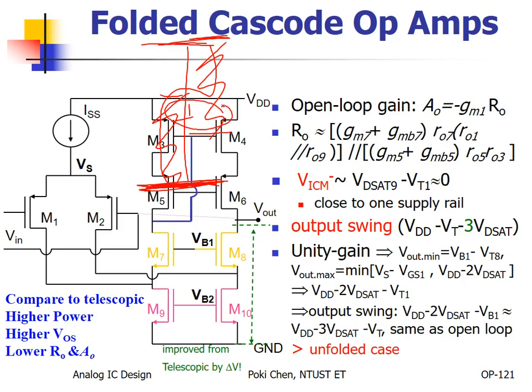Those differential inputs are active, are functional. So you get double gain in the middle. Only one gain here with NMOS. Double gain here with both PMOS and NMOS. And finally, only one gain here with PMOS differential input. Okay? But anyway, still better than not. You can fully operate from the ground to the VDD for the input.